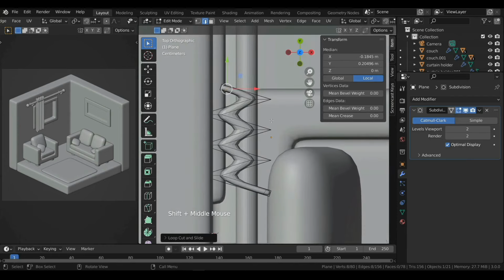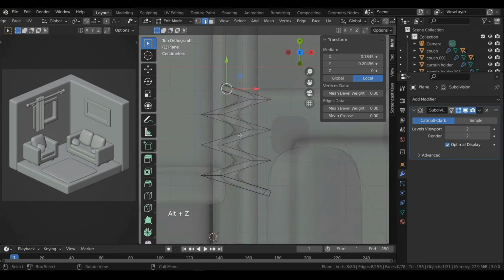If you look from top view, you will see that the edge outline is outside the rod, but the mesh is not due to the subsurf modifier. So in X-ray view, with edge mode enabled, select the edges. Then bevel them a bit with Ctrl+B.